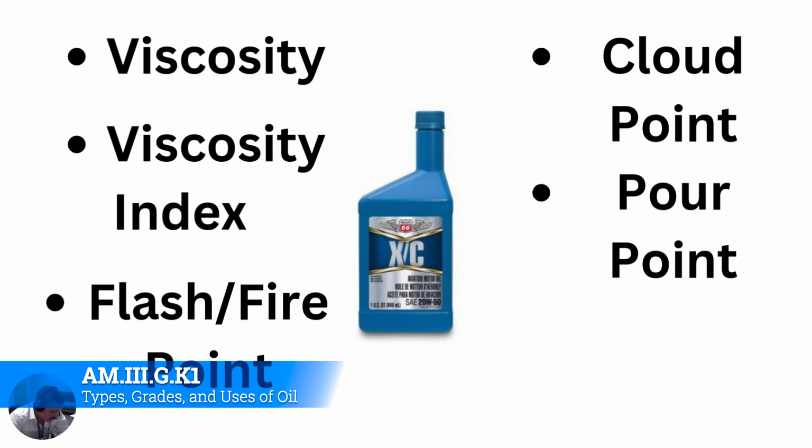Okay, now the pour point. The pour point is the lowest temperature at which the oil can be poured out, actually moved from one place to another. It doesn't necessarily become a solid, it doesn't necessarily freeze, even though it can. But it'll get so viscous that it's almost like a really sticky gelatin. That's when the temperature drops below the pour point. So oil has to operate above its pour point to move around inside of the engine. If not, the engine's basically beating some sludge at the bottom of the sump. So nothing good is going to happen there.